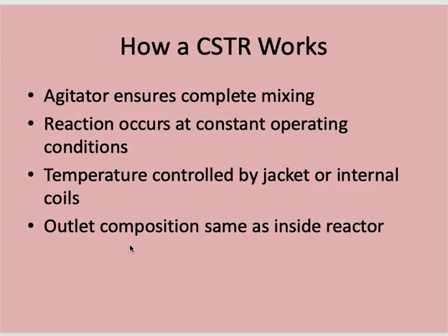How does a continuous stirred tank reactor work? The agitator ensures the complete mixing between the reactants. Reaction occurs at constant operating conditions normally. Okay, you stabilize the pressure or vacuum, you stabilize the temperature, okay, you stabilize the agitation speed. So the reaction occurs at constant operating conditions.